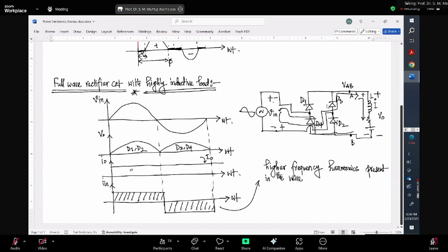So what is the detrimental effect of harmonics? Can anybody tell me? Sir, core loss will increase. So core loss actually depends on voltage and frequency. So if you see there are lots of harmonics that are being introduced by the highly inductive load, then you will find that the core loss is increasing, and this input power is actually coming through some kind of transformer.